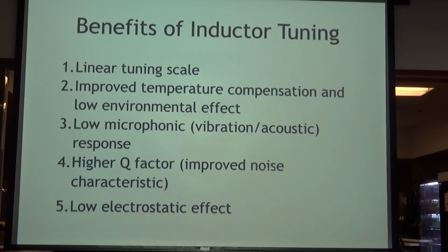Low microphonics. If you take a tuning capacitor, like most radios, the old AM radios and most ham gear, in fact, that didn't have a PTO, if you banged on the tuning capacitor, you could sometimes hear it, particularly if you're at CW. It's because you had all these little plates that would move back and forth, and that's not good if you had vibration. A higher Q factor, we'll talk about that in a little minute, and then low electrostatic effect. If you happen to have a wire passing by the capacitor and it's got some signal on it, it'll pick up the E field off that signal, whereas the inductor tuning design used a fixed capacitor, and you'd have to actually change the permeability or introduce a magnetic field in order to get the EMI into it.